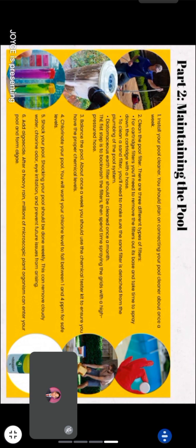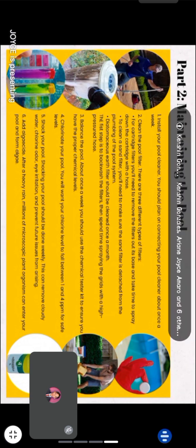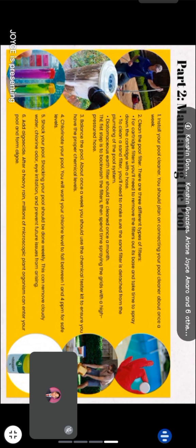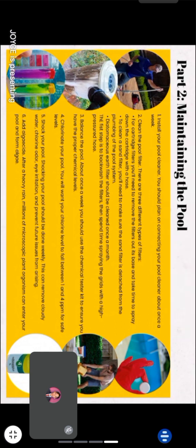So next is backwashing the filter. Once your waste hose is positioned, it's time to turn the pump back on and allow the pump to run on the backwash setting for at least 2 minutes. Then watch the side glass and turn the pump back off.